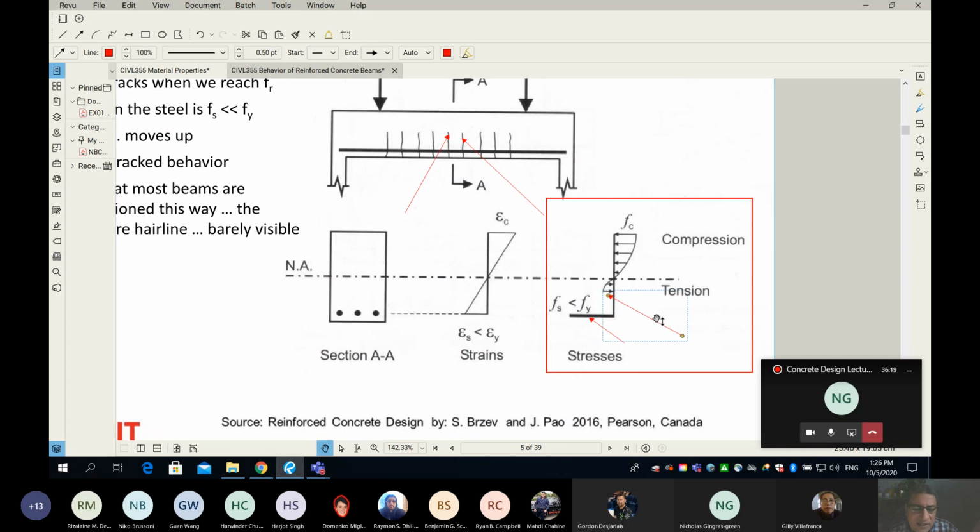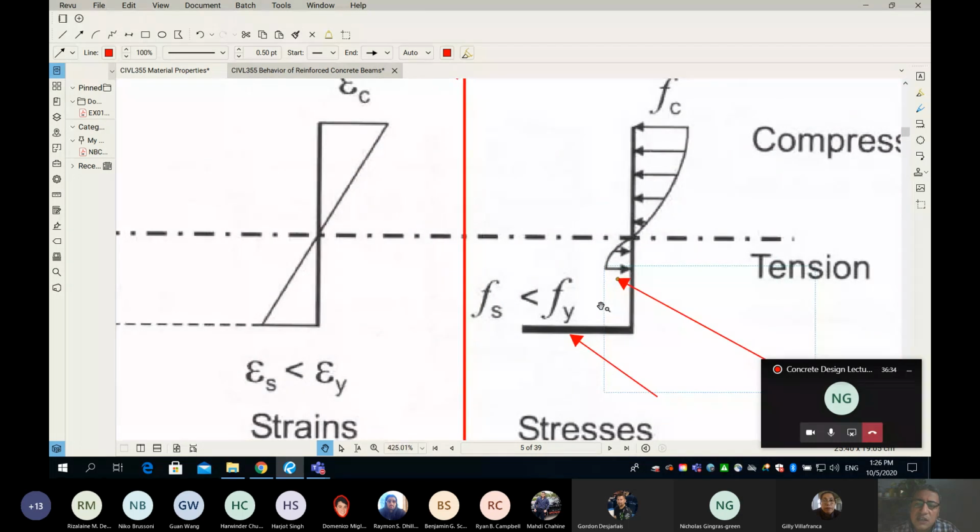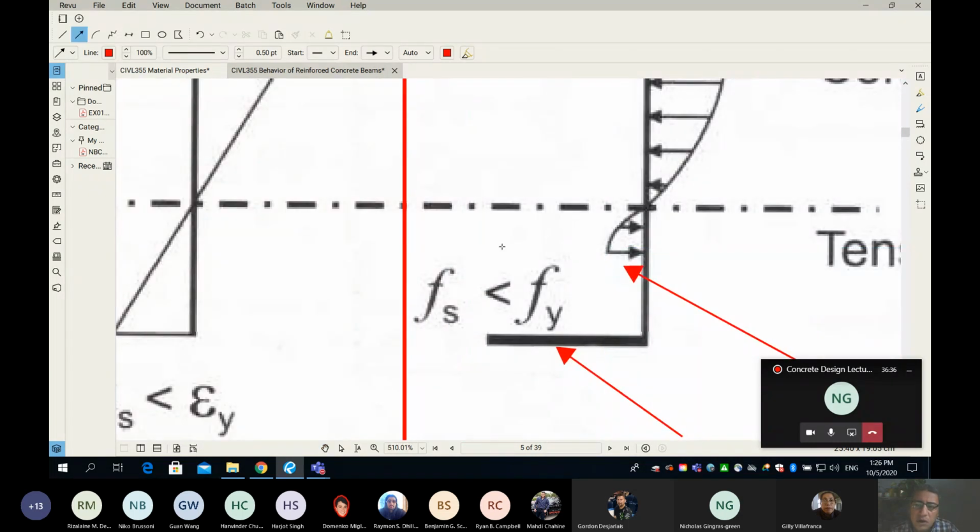And the thing is, which I'm going to say only one time: even concrete is not really good in tension. However, it still takes a little bit of tension, very little, like 3 MPa. And that's why you can see there is a little portion of the stress diagram which is here. So what's this part here? Concrete is in tension. The resistance is not zero. However, it's very, very little. And the rest is carried by the rebar.